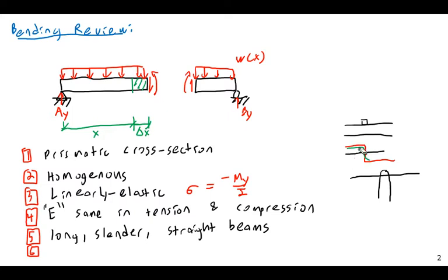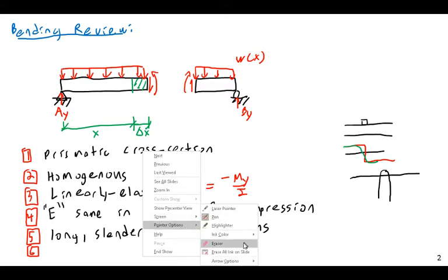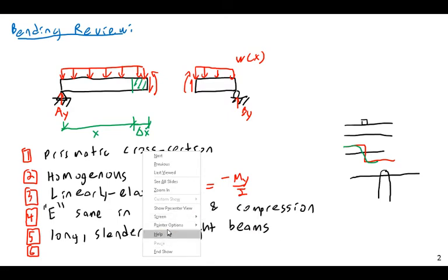If the width of this zone is very small relative to the member, you can approximate it as a vertical load, which we usually do. But if your beam is very short, that point load assumption breaks down, and we have to analyze the beam using other methods. So when we design beams, we are often assuming impossible conditions.